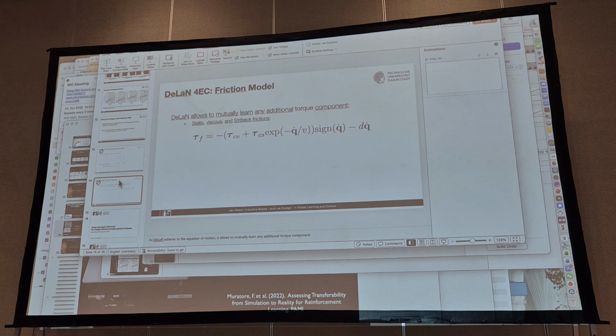Yes. Now my question is, if you apply such a methodology to an energy shaping approach, like for instance IDA-PBC, which we discussed with Federico before, in that case you have to solve some matching equations, but the assurance that the closed loop system is a port-Hamiltonian system tells you that the system is passive too. Now, since you are not sure that your system is exactly a port-Hamiltonian one, how can you ensure that passivity is fulfilled?